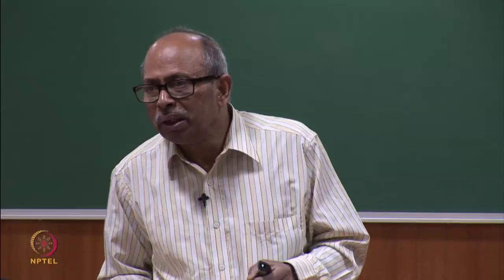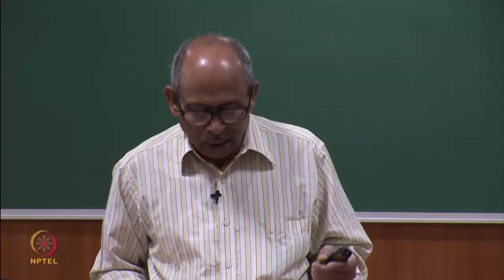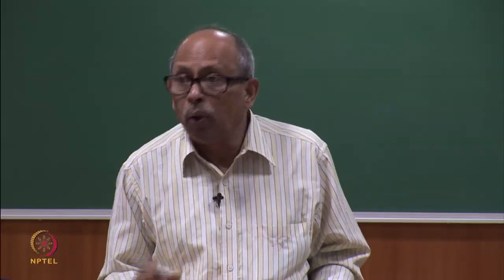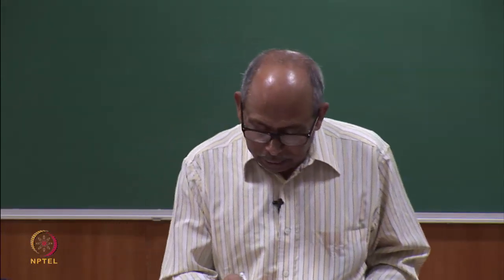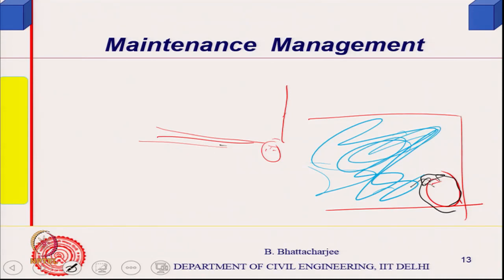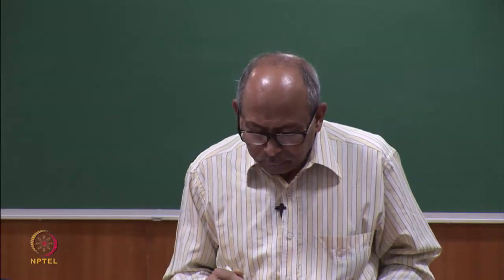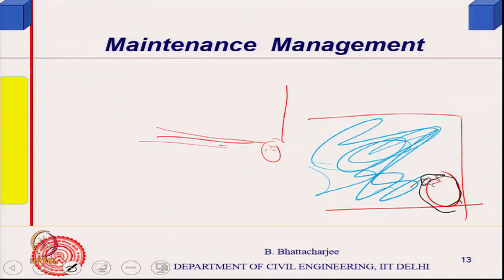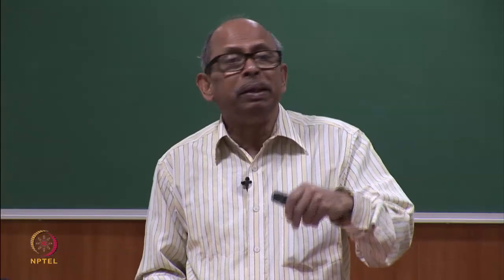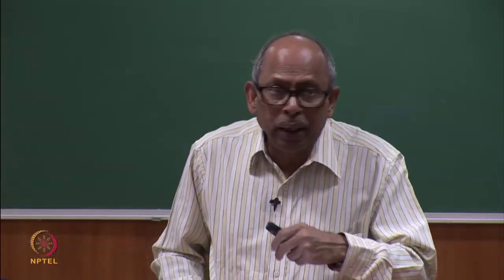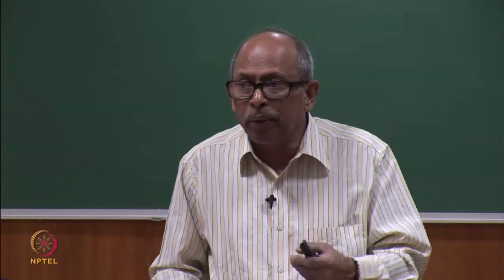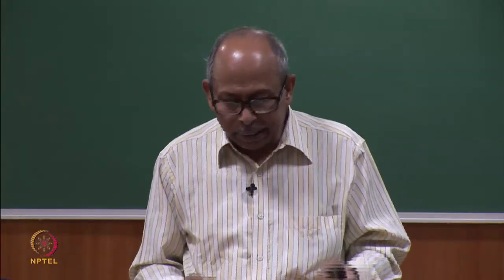When it should have drained off straight away, you will find that it takes long, or sometimes it simply holds, or some other very peculiar sort of construction detail problem comes. So, if the water is stagnant here, standing there for a long time, it would have a tendency to cause seepages in the long run. The flooring that would be exposed to water for a longer period of time, absorption, capillary absorption, etc.